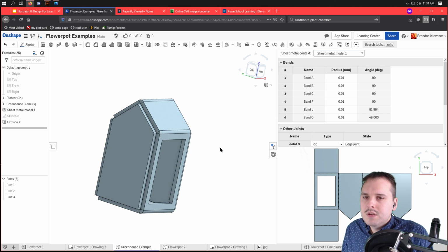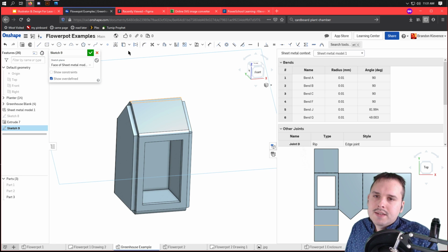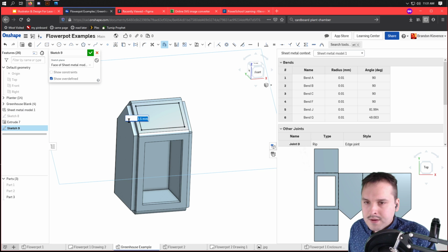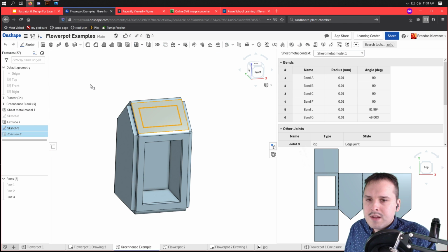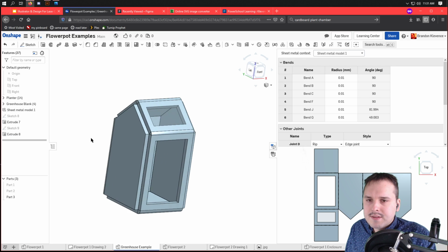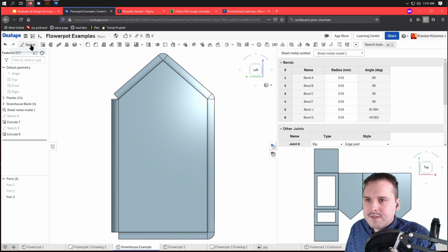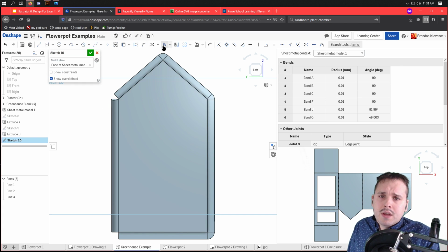Quite simple, hopefully super easy. To do the same thing again, up here: sketch, offset, bring it in, hit enter, 6 millimeters is what I want, and then extrude again. Hopefully it automatically thinks it's an extrude remove. We're done with that. So we're going really fast right now, which is good. It's real simple and easy in Onshape. We're actually using some solid tools right now.